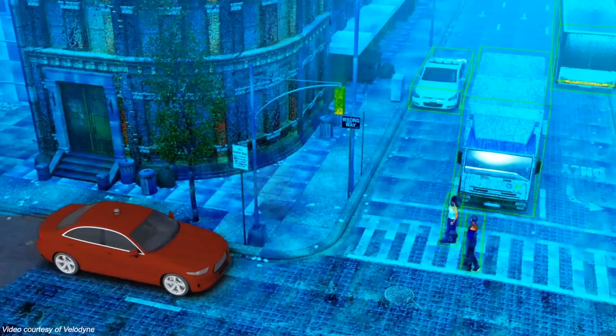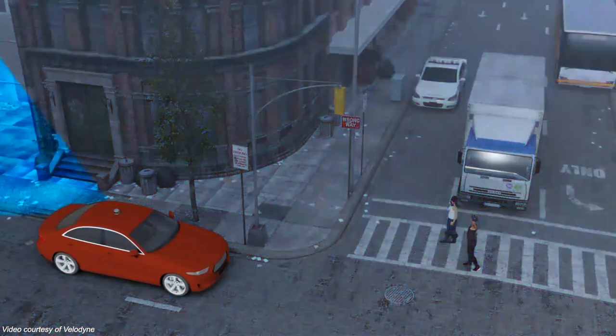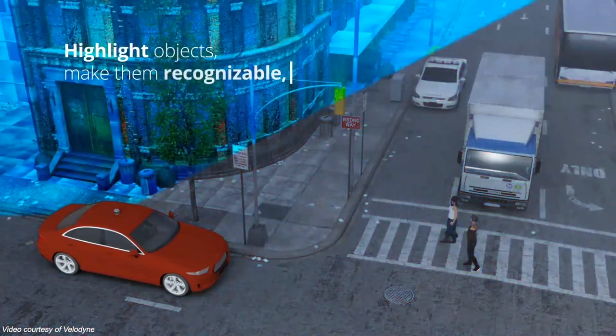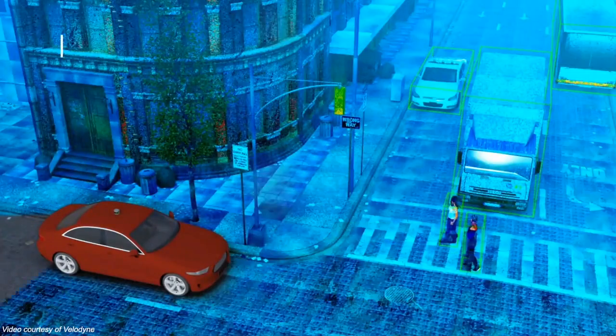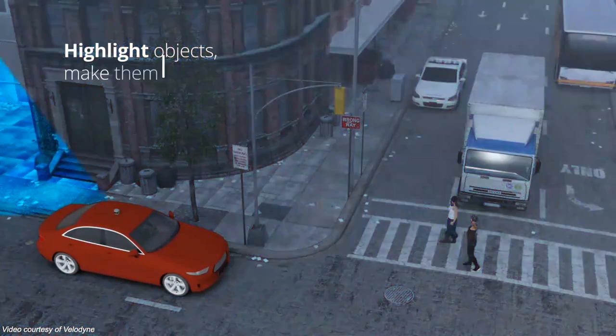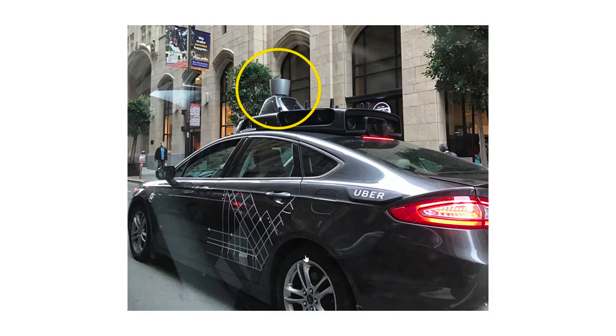The multiple LiDAR beams provide much more information than a single beam LiDAR in highlighting objects, making them recognizable and showing movements. Actually, LiDARs are currently the sensor of choice for most of the automotive industry developing automated vehicles. Here you see an example of a vehicle with a LiDAR mounted on the roof of the car, with other sensors mounted on the roof as well. As you understand, the design of vehicles including 360-degree sweeping LiDARs are likely to be somewhat different from the traditional sleek roofs, as the sensor needs to be high enough to cover areas close enough to the own vehicle.